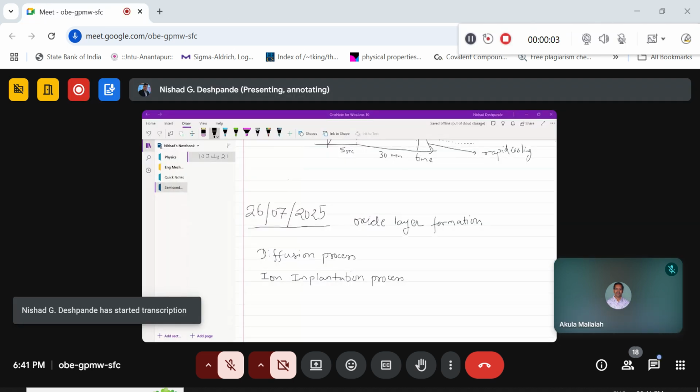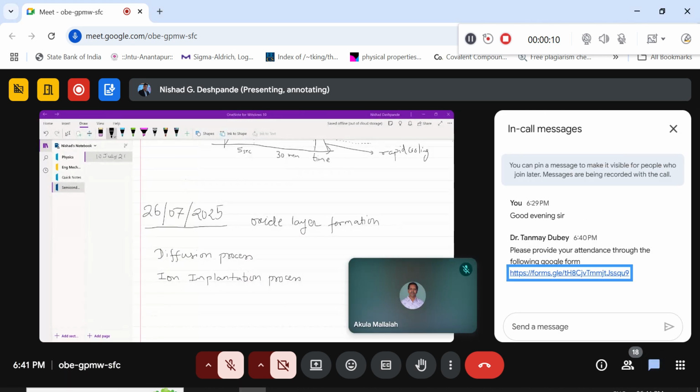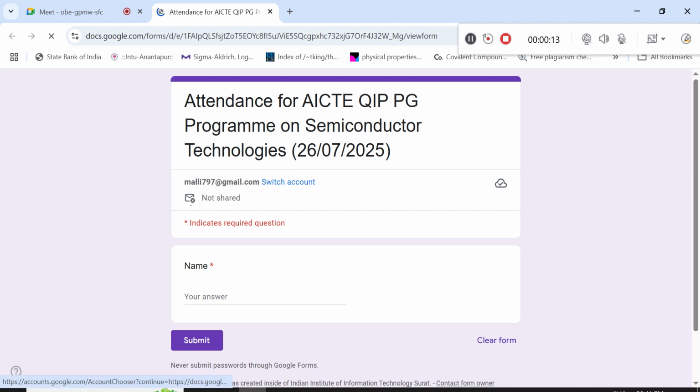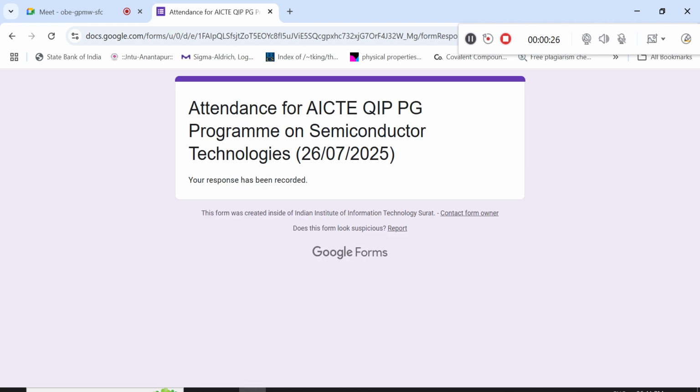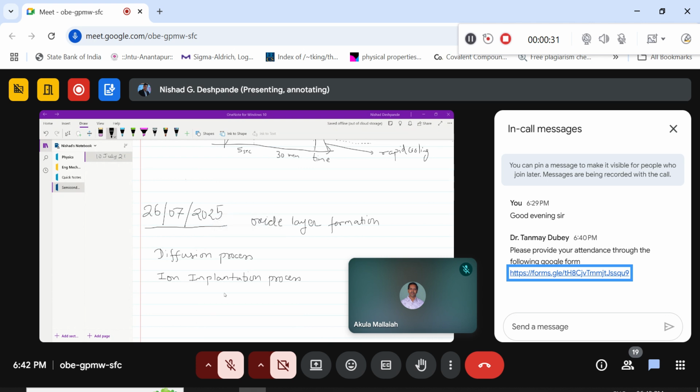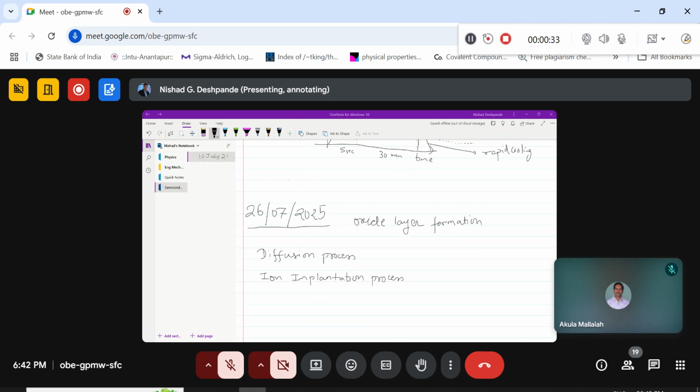Lectures. So we were discussing these growth mechanisms, kinetics, techniques, and effects of the oxide layer formation on the silicon die. We were talking about how this particular metallization and these layout designs can be possible. We were discussing different thicknesses. Different thicknesses will be useful for different application purposes, so accordingly, one has to have very good control over the thicknesses in order to properly get a device that is required for our end outputs.